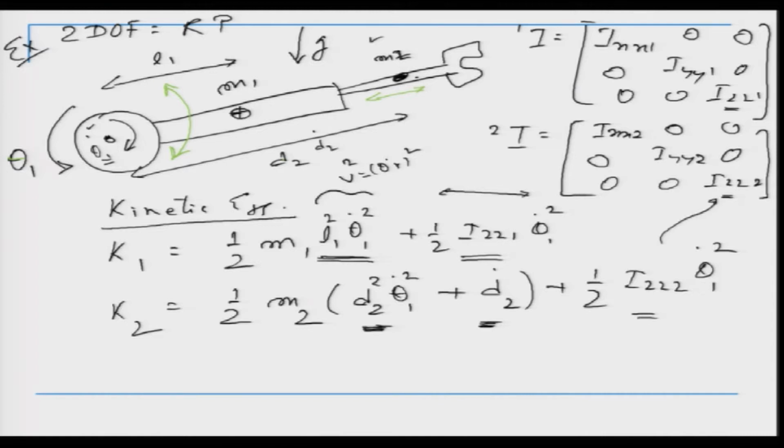Okay. So, now this is the kinetic energy, and this is half m v squared. So, there is going to be a squared term here, right. So, this is our kinetic energy, plus the potential energy. So, the total K1 plus K2 is equal to half, I just take the sum of this, which is m1 L1 squared. I take theta dot squared common. So, there is a theta dot here, here and there.